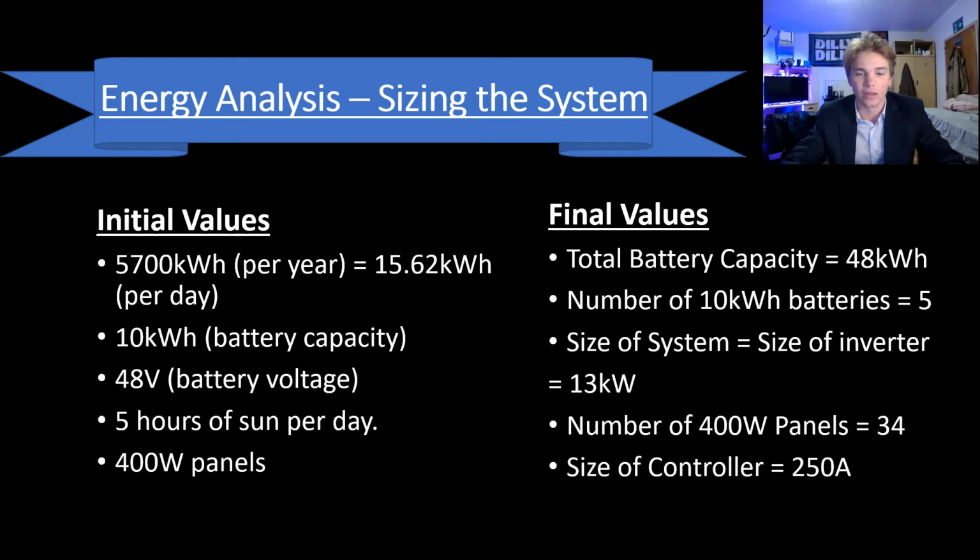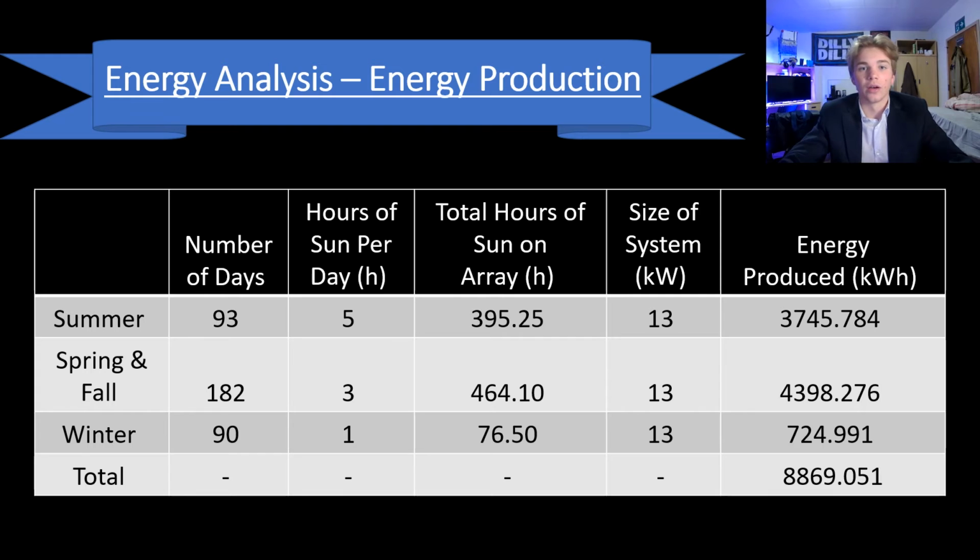And lastly is the size of the controller, which is also a trivial calculation of dividing the size of the system by the battery voltage. Secondly are the energy calculations done for energy production.